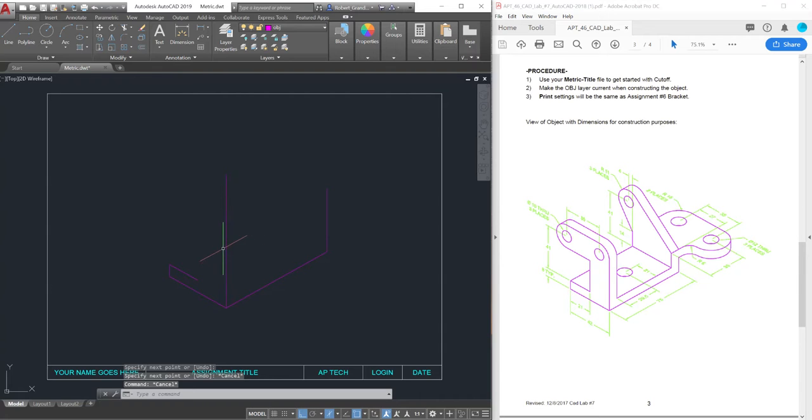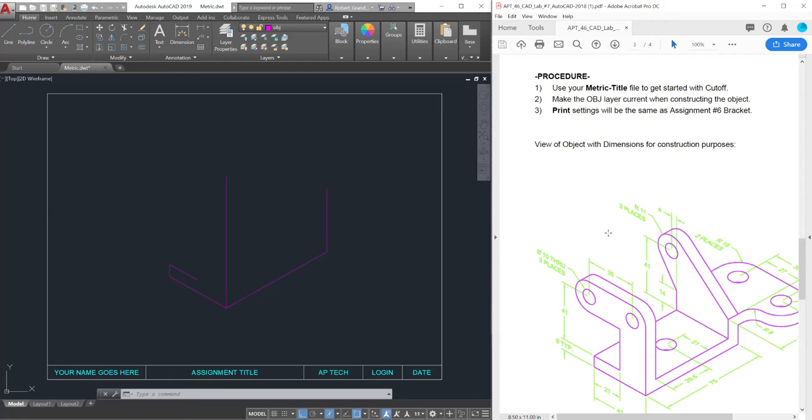Now what I'm going to do is try to figure out how best to place these two ellipses that we see here. When you work in CAD, it is not like working in paper and pencil. You can do things that make precious little sense when you're drawing with paper and pencil. So, if we look at these two ellipses here, I can see that the center of them is 41 millimeters up from this corner here, and I can see this one here is 35 millimeters away from this one, so that's the distance apart on these two. Let me zoom in there a little bit so we can see it better.